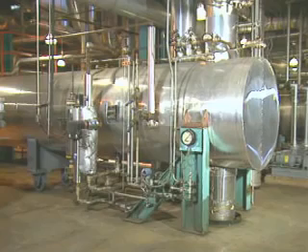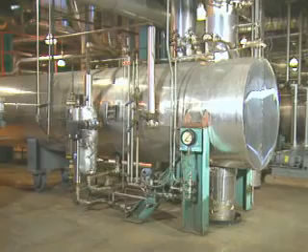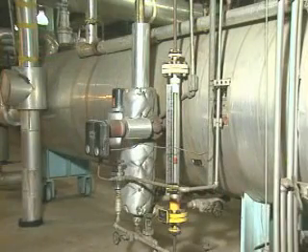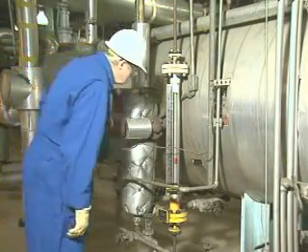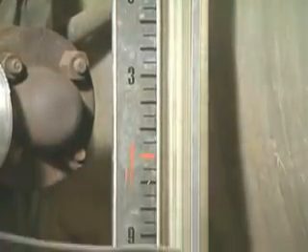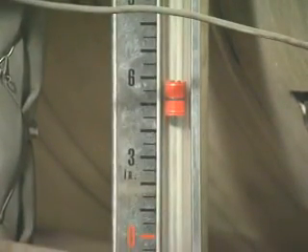We'll look at some operating checks for a high-pressure closed feed water heater. Most of the checks for this type of heater also apply to low and intermediate pressure condensate or feed water heaters. To monitor the level in the shell side of the heater, you can usually check a sight glass on the heater. An abnormal level in the sight glass could indicate a problem that should be reported.